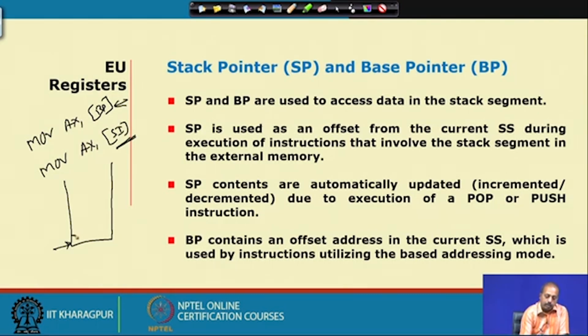Currently, say you have this stack segment register here, and memory addresses are decreasing in this direction. The stack segment register is put to the maximum value, and the stack pointer register is made equal to 0. Now, whenever we do a push, this value will become -1, so it will be decremented by 1. You will get the location where the value will come in a push instruction.